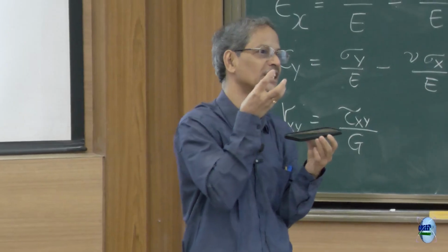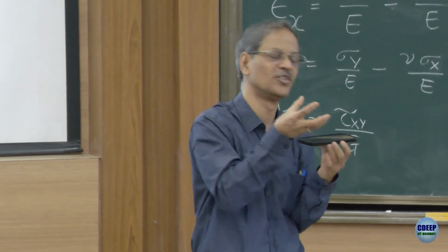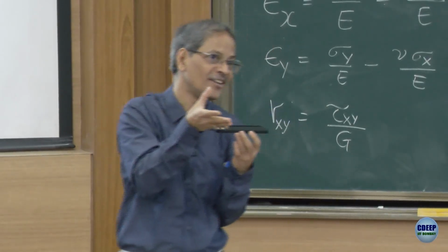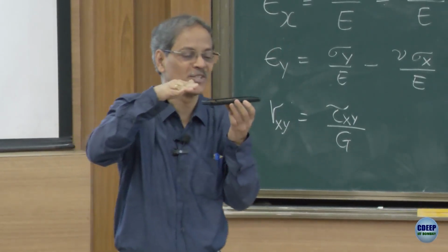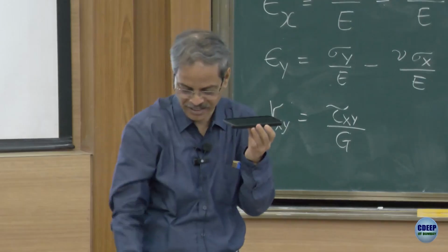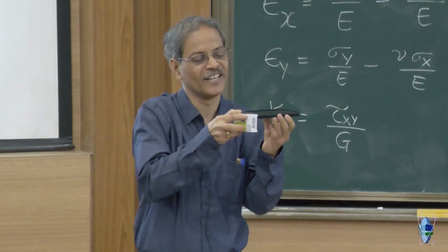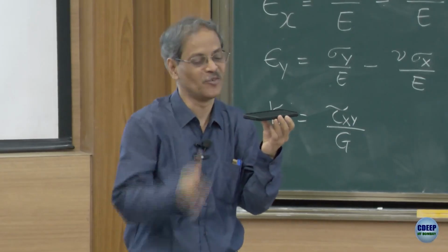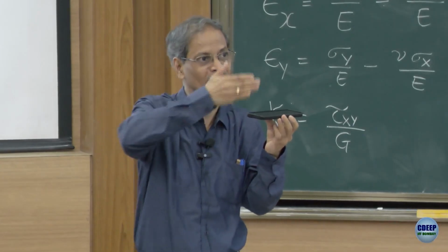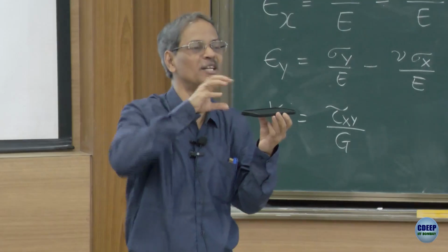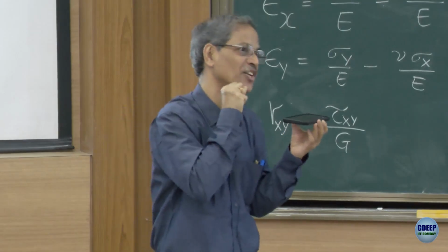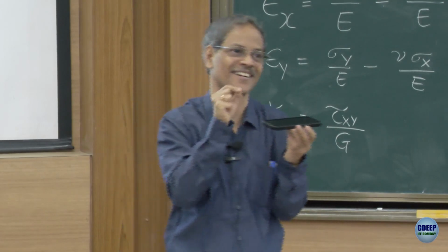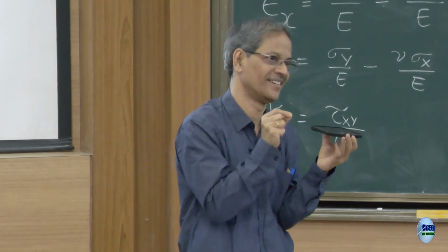Whether there will be concentration of stresses, leading to a shoot up in the stress values and then ultimately failure, will depend upon how much fillet radius you have given. If two objects are joining, if you have welded them, how well you have given the fillet radius or chamfer will determine how much the stress is. Now I cannot simply ignore that. I have to model that geometric feature accurately.